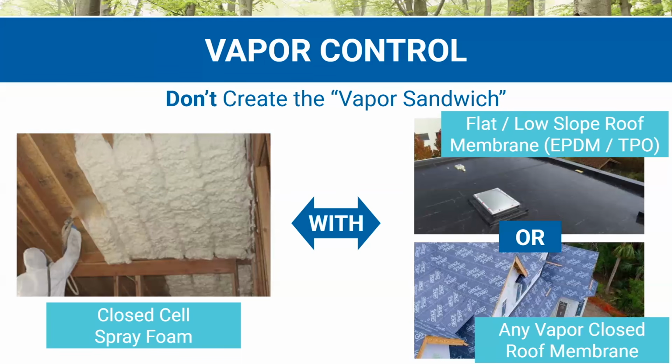So as that wood framing swells in the summer and then shrinks a little bit in the winter, the foam can't move along with it. And now we get these voids and cracks where that foam is meeting the wood, and the foam can trap that moisture and be very problematic. Or where that void is all the way through, and now our warm interior air is moving through and condensing on that cold surface still.